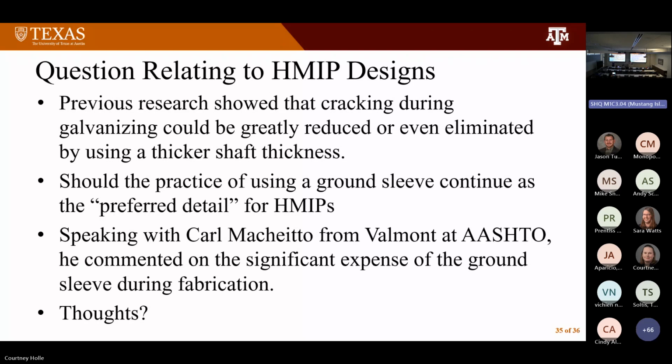Then I had a question about the CCSs also, because you showed a picture about the gravity loads and how on the tensile side, but on the CCSs, the wind is far more significant than the gravity load. Is that it all the way around? We're inspecting everything, but we're just trying to say where are the cracks that we're finding. When you look at the CCS, you've got wind hitting the sign that's putting torsion on it. You've got some bouncing because there's a little bit of galloping that ends up happening as the pole is there.